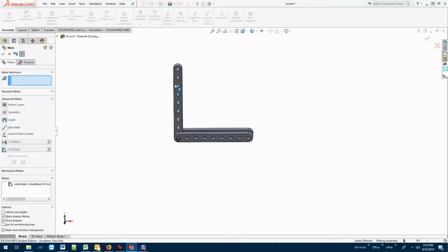That is actually more work on SolidWorks than setting up a mate. So if I were to have a physical piece here and I told SolidWorks, look, let me know every time I run into that piece, that is much more strenuous on your computer system than just setting up the mate to say, hey, limit the angle. Limit the angle so that this thing cannot go past 90 degrees.